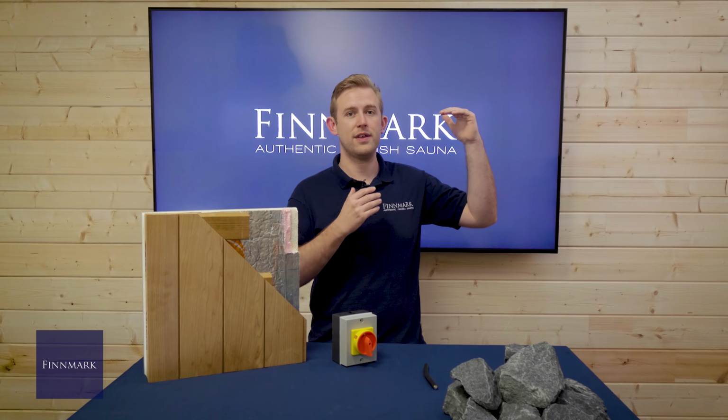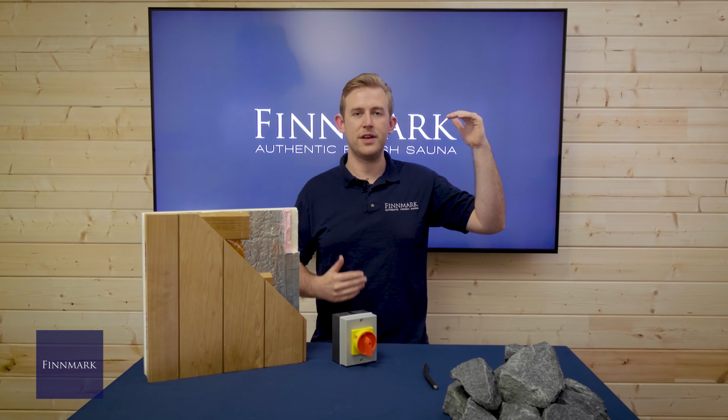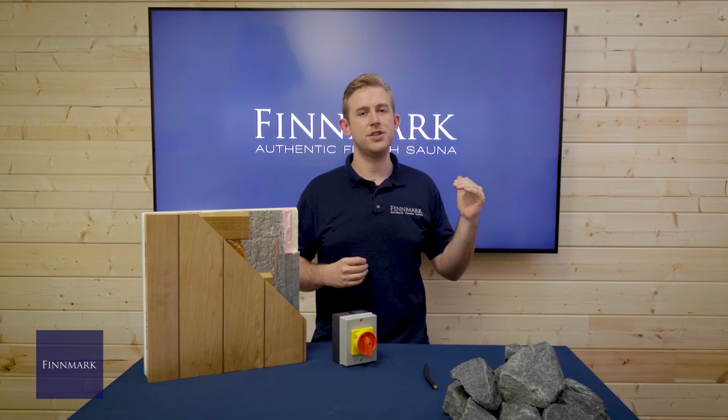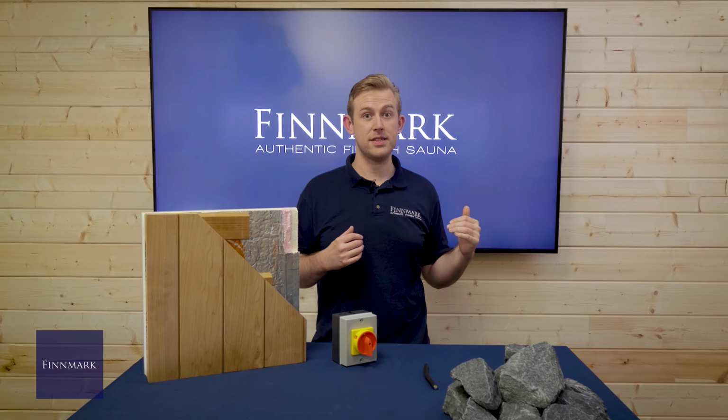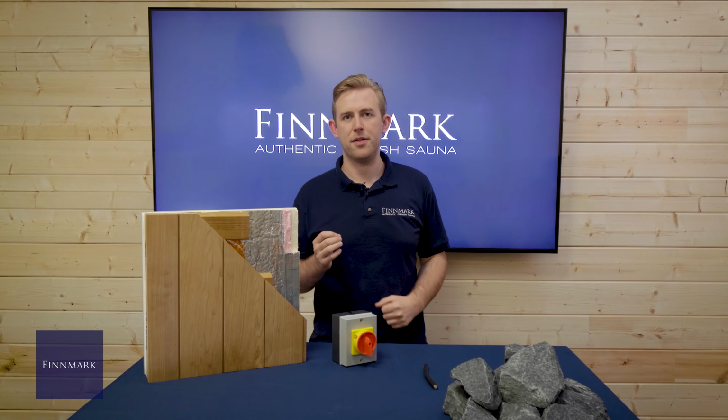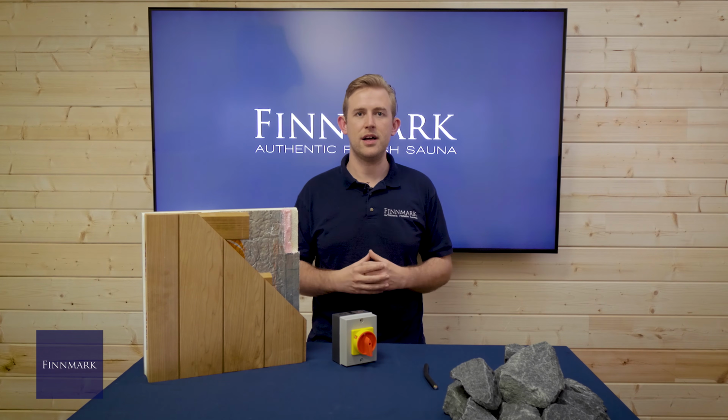In a typical domestic sauna, we at Finnmark look to have the following elevations. The ceiling in the sauna should be 2,100mm from the finished floor level, the upper bench at 1,050mm from floor level, the lower bench at 600mm, and a step at 300. Naturally, in larger or commercial saunas, where 2 or more tiers of benching are required, these heights can be adjusted to suit.